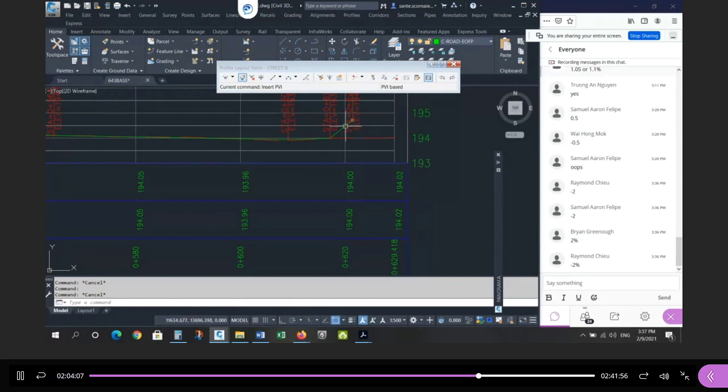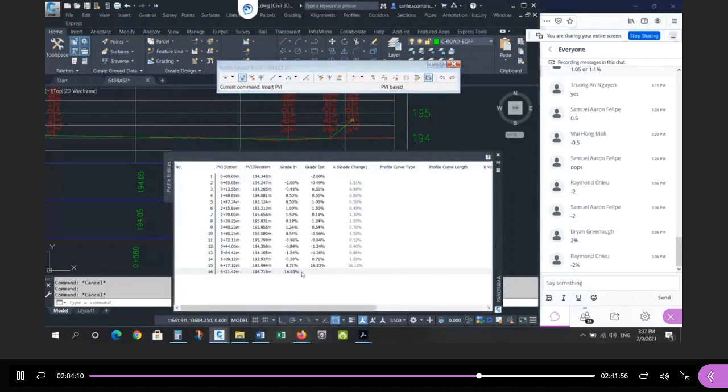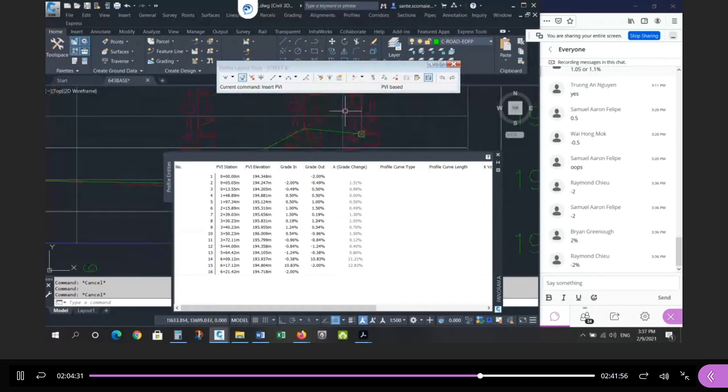The slope here is 2%, but what do you type into here? You have to type in the slope as defined by the direction of increasing chainage. So even though we're designing backwards, the slope's plus and minus sign is based on moving forward. So if I put -2% here, watch what happens. -2, it's downhill, it's wrong. Right?